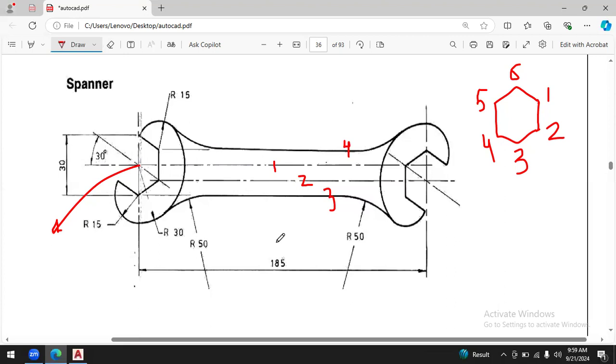Whereas keeping this distance in mind, you can draw easily all four lines. Just take 185 as the length of their lines. So originating from the reference point 0, 0, you only need to draw one straight line on 0-degree angle that is of length 185. So just go for it.